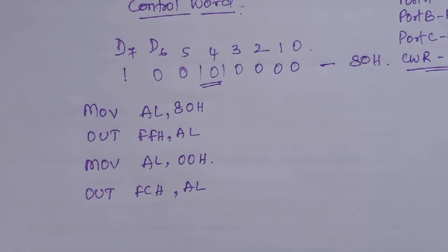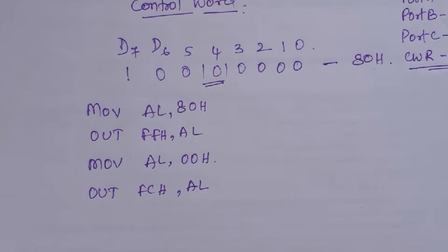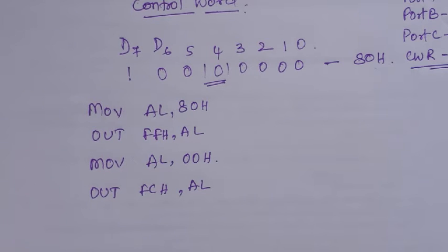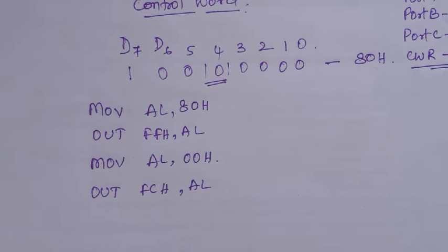One more point is, if we continuously increment this and send to the output, because the processor speed is more, like we give 8 megahertz or 10 megahertz clock to the processor, the conversion from 00 to FF increment and conversion to analog takes very small time, so it will not be visible. The waveform will be of very smaller amplitude that we cannot make out.